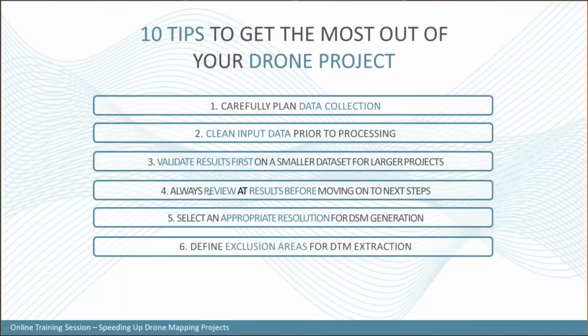Define exclusion areas for DTM extraction. So let's say if you're seeing your overall project, maybe you want to define exclusion for bridges or for areas you want to keep intact in your terrain model. So that's one other thing.